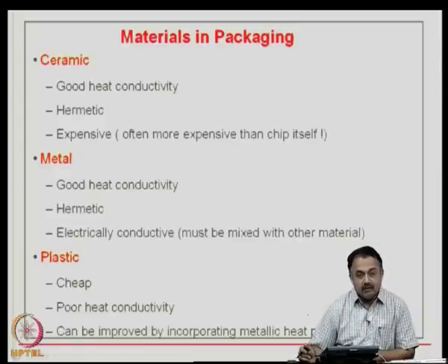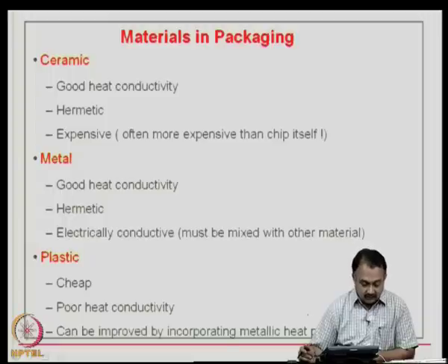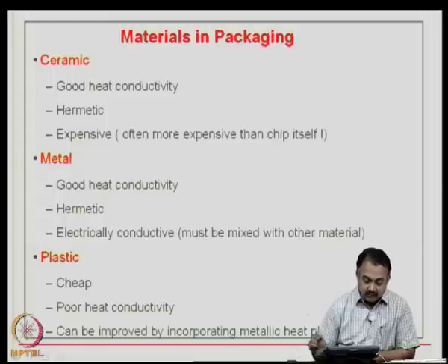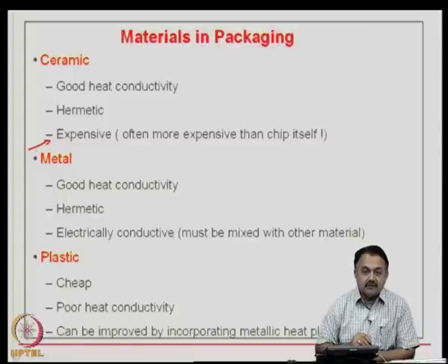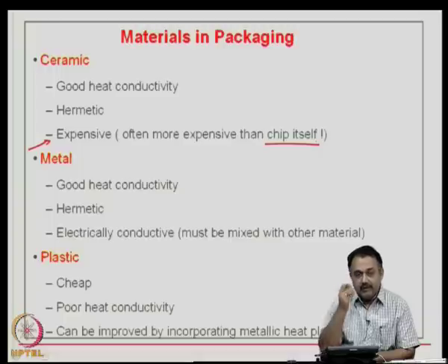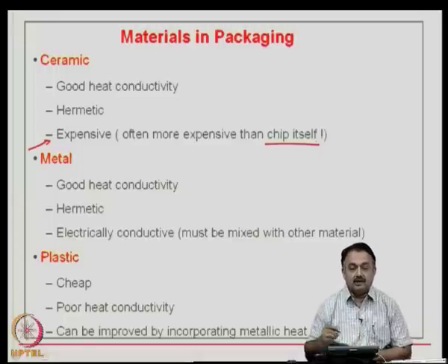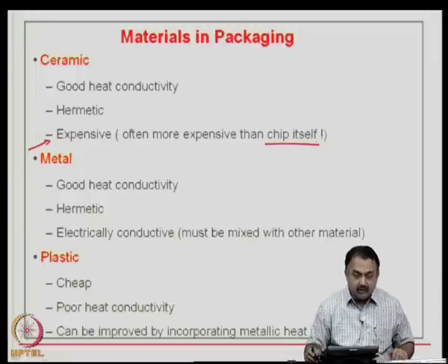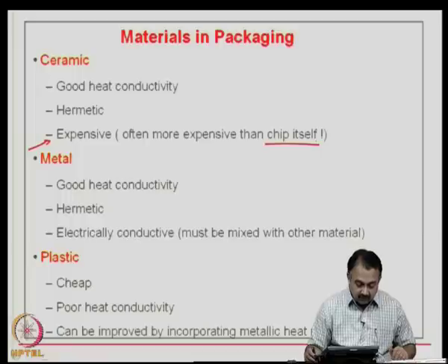If you are using ceramic, it should have good thermal conductivity. It should be possible to hermetically seal the packages with ceramic. It is expensive compared to plastic packages, often more expensive than the chip itself. Therefore, you must be wondering, why do we need a ceramic package? But as I said, in certain areas like military, space, avionics and so on, reliability is more important because of high performance. Therefore, people go in for ceramic.